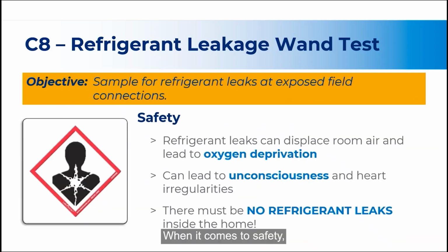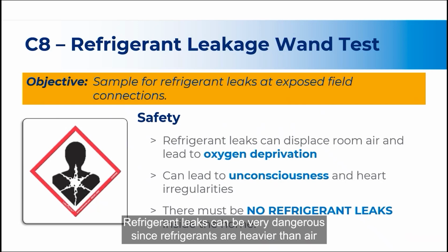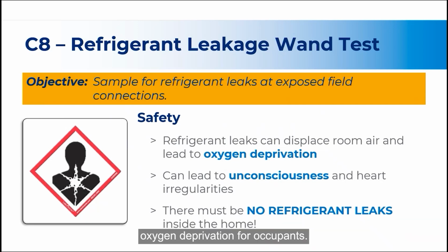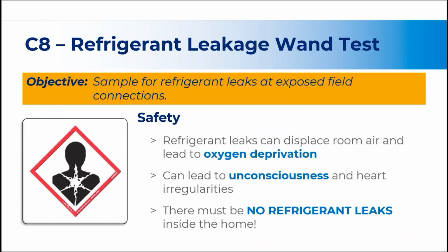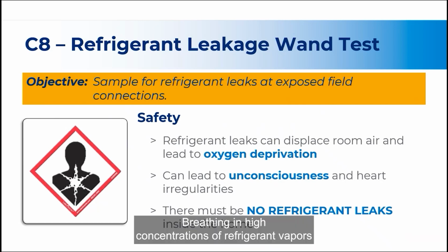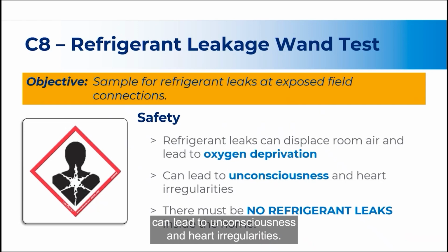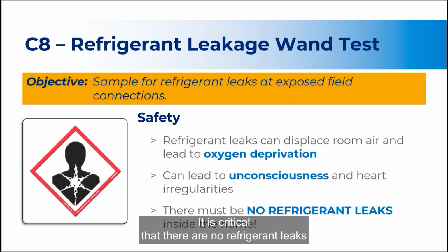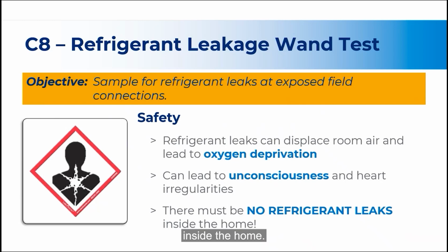When it comes to safety, refrigerant leaks can be very dangerous. Since refrigerants are heavier than air, refrigerant leaks in an enclosed area can displace room air and lead to oxygen deprivation for occupants. Breathing in high concentrations of refrigerant vapors can lead to unconsciousness and heart irregularities. It is critical that there are no refrigerant leaks inside the home.